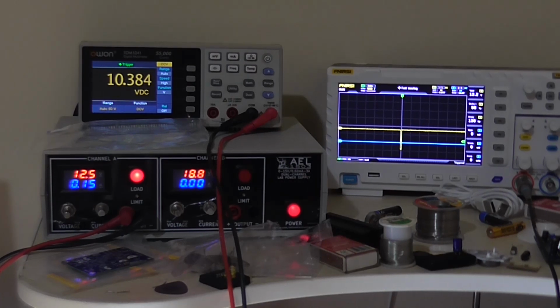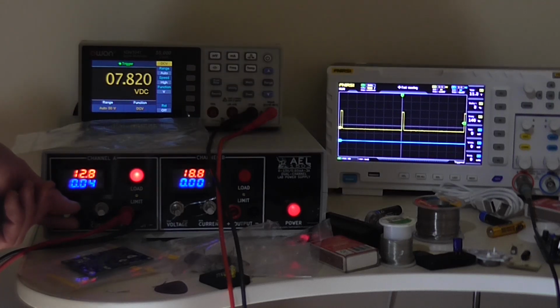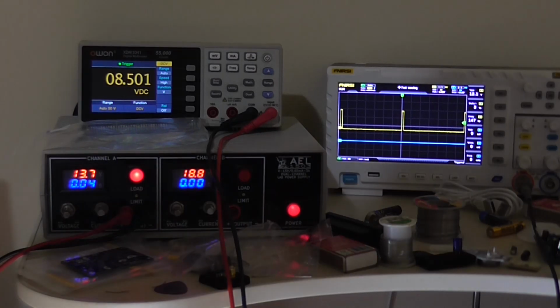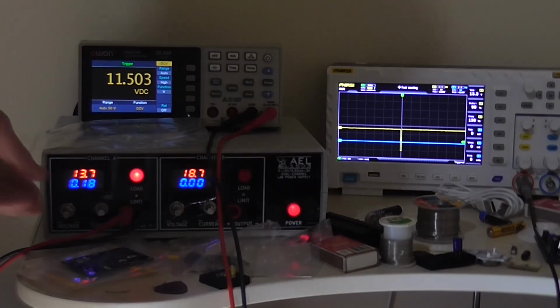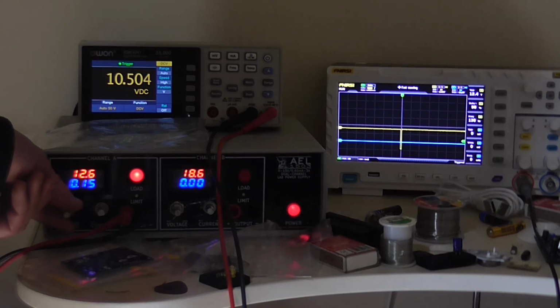So if you up the voltage a little, you can compensate, but then again, that'll also affect the low end speed as well. So if I put it on the low and I up the voltage in, it's about 13.6, it brings the voltage up at the low end as well. But we're at 11.5, which is closest to 12 volts that we need. And if it was running in a car, then yeah, it would work effectively, because when the engine's running, that's going to be close to 14 volts.